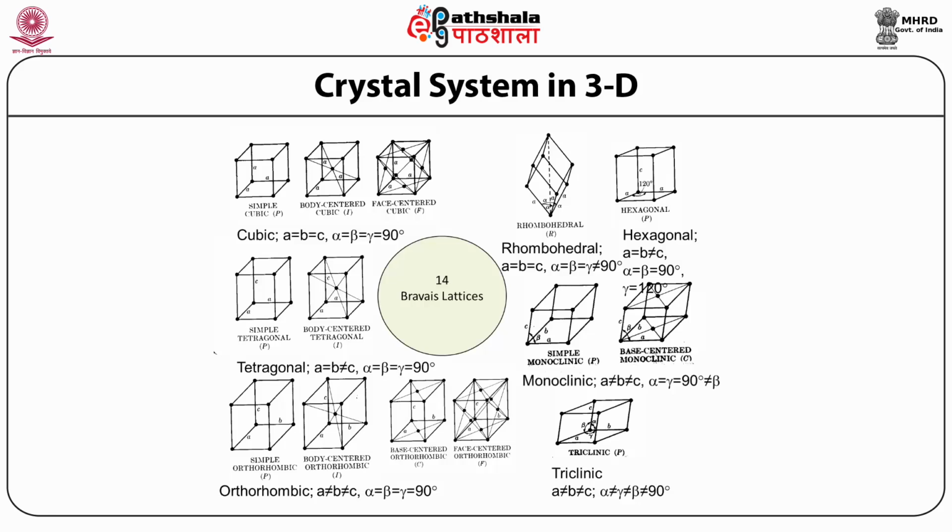One crystallographic axis is taken parallel to the direction of the two-fold symmetry axis, and the other two axes must therefore be perpendicular to it. The choice of the cell is therefore restricted to a parallelepiped having 2 right angles. One angle has to be specified, hence the name monoclinic. Similarly, the other structures, that is orthorhombic and tetragonal structures, have already been discussed and are mentioned in this slide in detail.